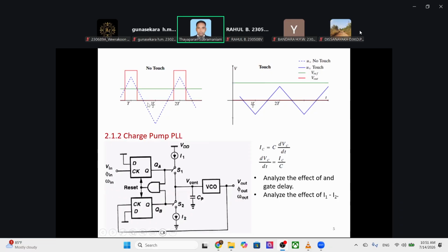Say this is the threshold we get. The peak voltage will reduce because of the additional capacitance. The time constant RC increases as the capacitor increases, therefore the peak voltage reduces. If we take the midpoint as the threshold reference, the peak voltage will not cross this reference because of the external capacitance, right? So that is the detection.